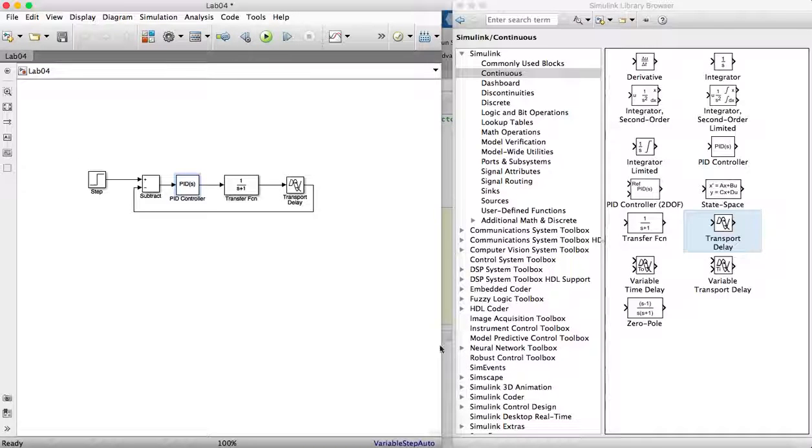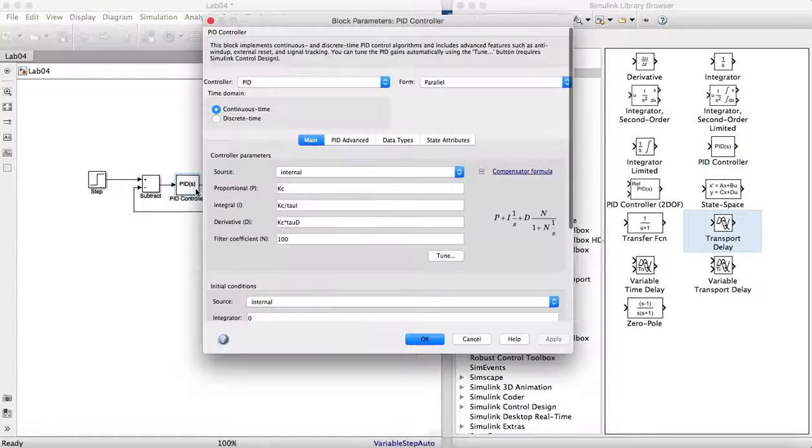What about the theta? We know that before the theta, we have the transfer function. Once we are done configuring our controller tuning parameters, the next step is to limit the output, because usually in real life, for example, if we have a valve or pumps, they have some maximum and minimum possible outputs.